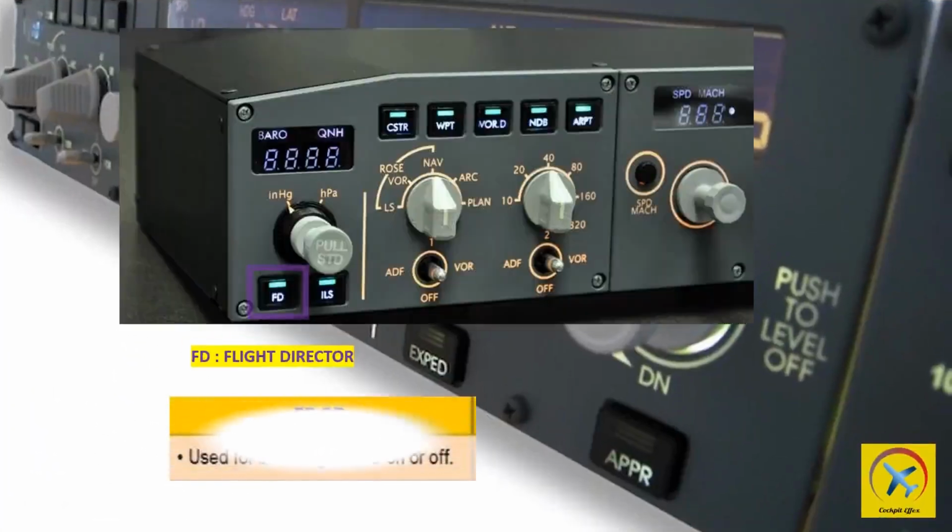The FD button when pushed cycles the flight director command bars on or off. The FD button illuminates green when selected on. FD2 annunciation indicates that the captain's FD is selected off and the flight officer's flight director is selected on.